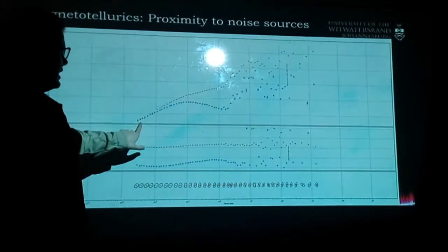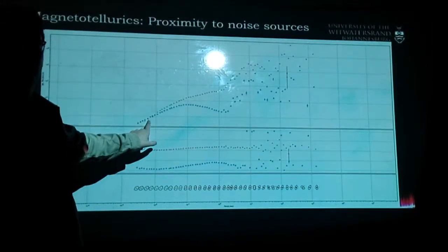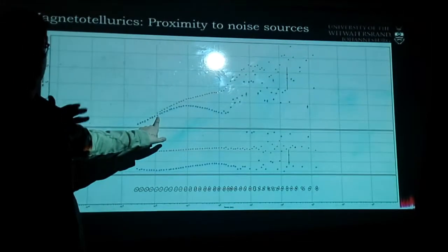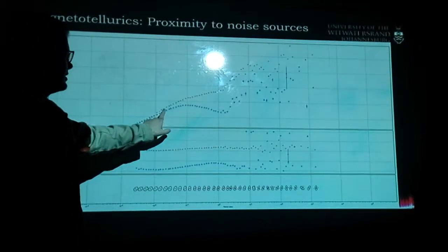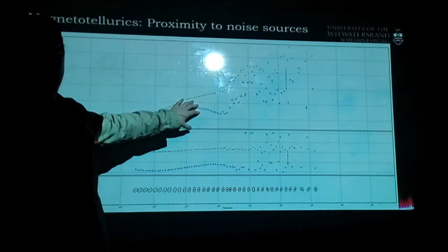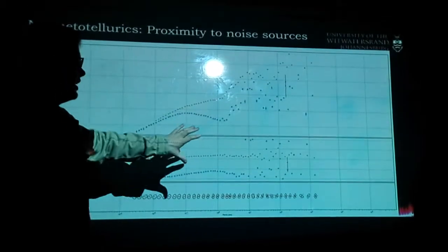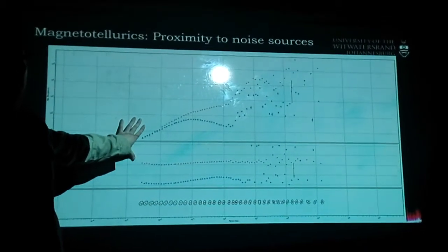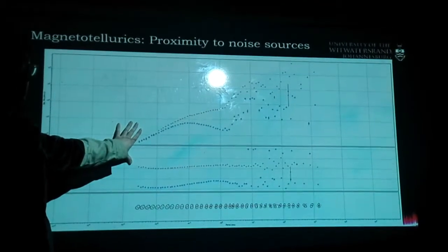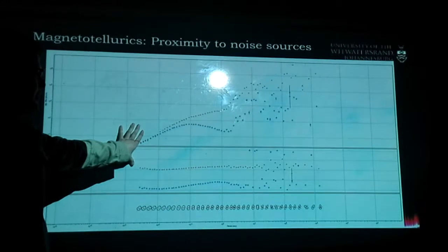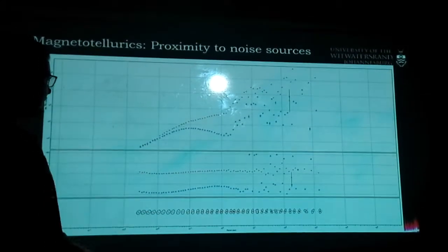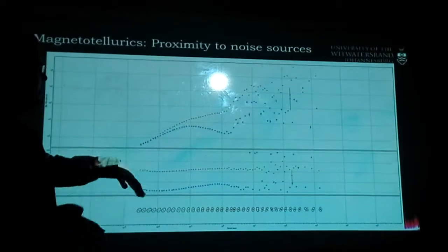Initially at the near surface it's quite 1D, your lithology, showing the overburden and then the sediments, and then we get into 2D structures, which could be contacts, faults, anything like that. Just looking at your data, you can tell a lot about what's underneath you before you even process or convert it. That's what's nice about MT data. I think the red is the TE and the blue is the TM again.